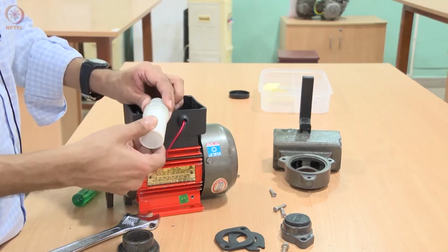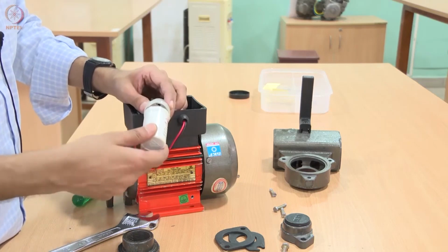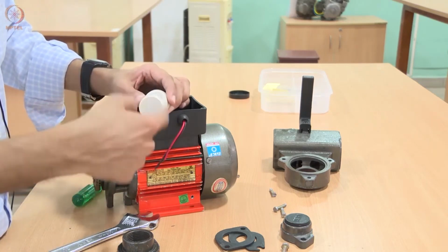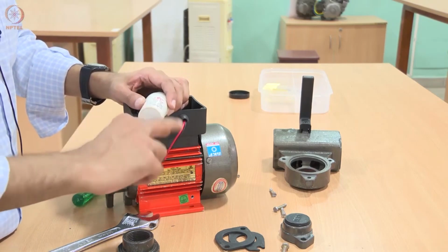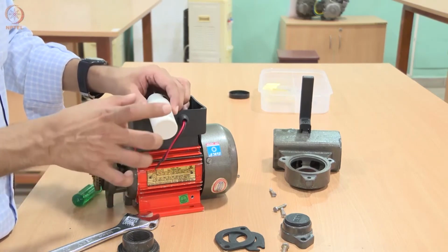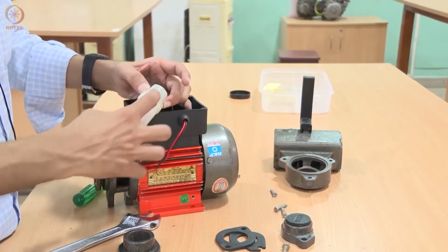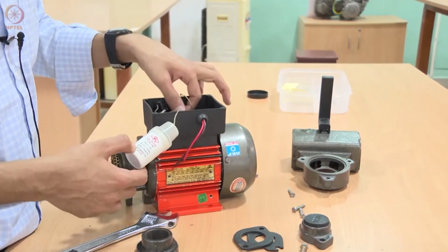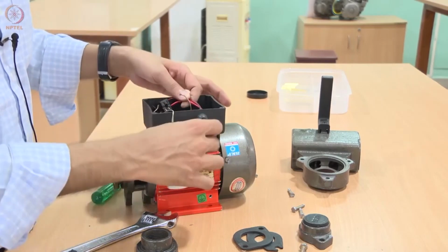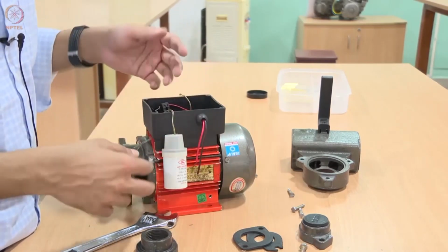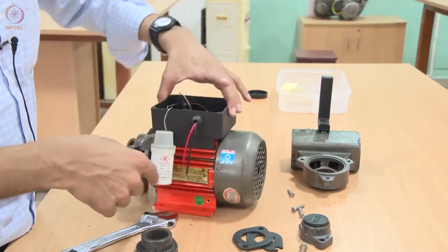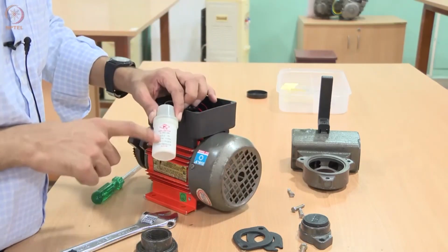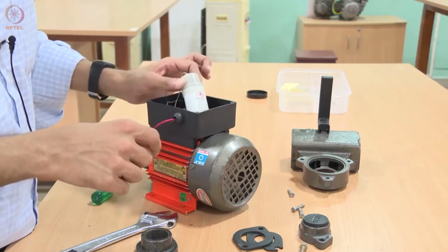These capacitors are called electrolytic. You can see there is a coil of parallel plates in coil form, and there is a dielectric that fills it. This capacitor is connected to the starting winding, and the other line is connected to the running winding. So basically you have two windings. Occasionally, every 3 to 4 years, you may have to replace the capacitor as it gets old.